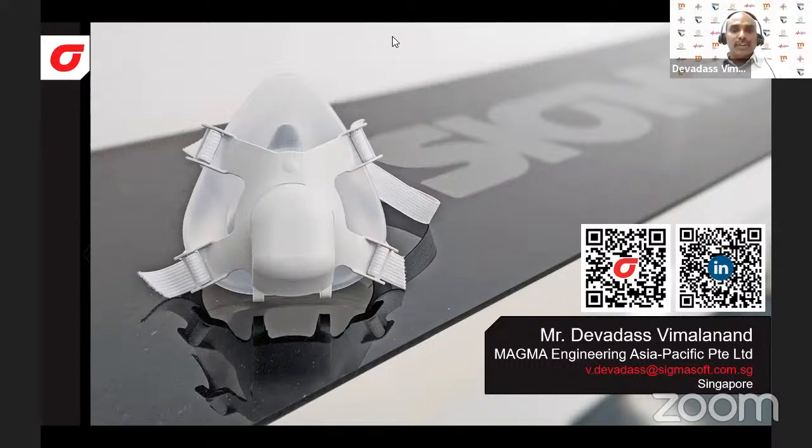So we need to know the purpose of the simulation. Is it to understand the filling behavior or the solidification behavior? Let's say you want to find out the cycle time, then you can use the simulation without the mold. But if you want to understand the heating distribution of the mold, and how this heating distribution affects your cycle time or the product quality, then it is necessary to include the mold.